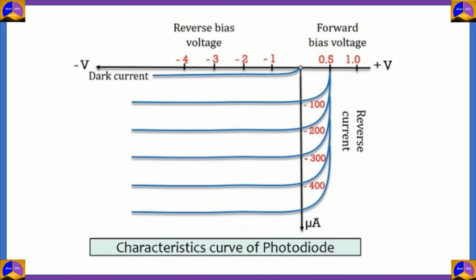So in a photodiode, the dark current is normally measured, and so when light hits a photodiode, because of the reverse bias voltage and the formation of the electric field, there is extra current flowing through the diode, which means that an electrical signal can be generated if light falls on a photodiode. Therefore, photodiodes are used as light sensors, and also they can be used for sensors such as the ones for IR, UV, etc.